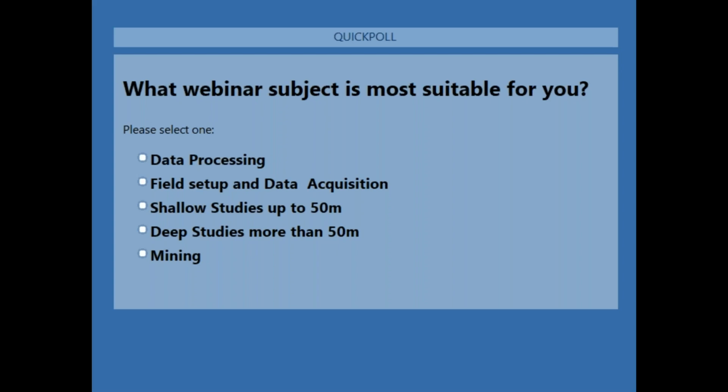Try to keep contact resistance less than 1,000, 2,000, or 1,600 ohms. That will give you better IP measurement. Otherwise you will get noisy IP data if your contact resistance is very high. So pouring water, salty water, or bentonite solution will reduce your contact resistance.